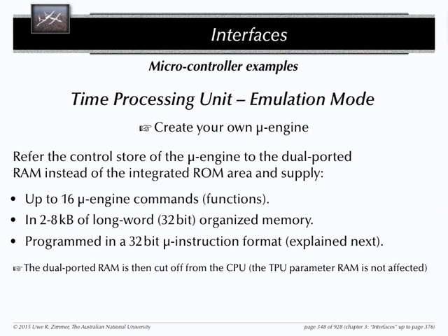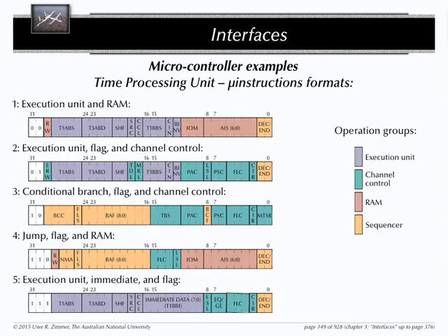We can have 16 different functions in total, which this thing can fulfill. And 32-bit wide micro instructions. That sounds scary. Good news is, this thing has exactly 5 instructions. The bad news is, they're damn complex. Because as often in these microcontroller environments, if you program with instructions directly on these controllers, a lot of CPU parts are programmed at the same time.